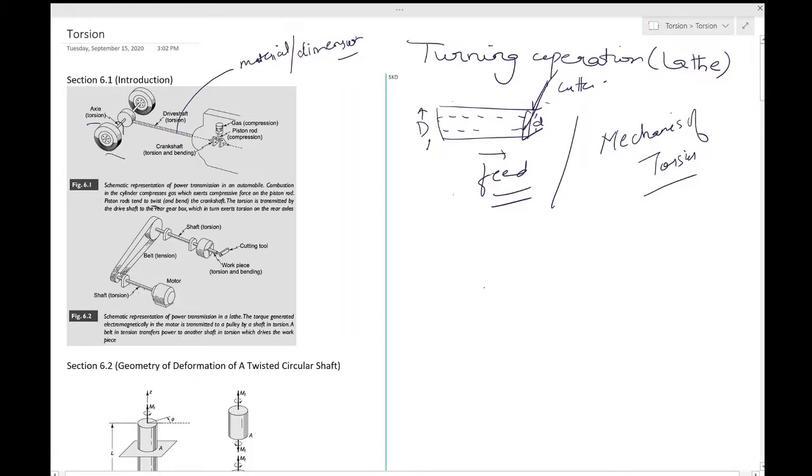How would you do that? You would have to find the stress using the elasticity concepts. You would find the stress tensor at any given point, convert it to the principal system, and then use those principal values to test your failure theories about whether it will be able to sustain this or not. The same would happen over there.